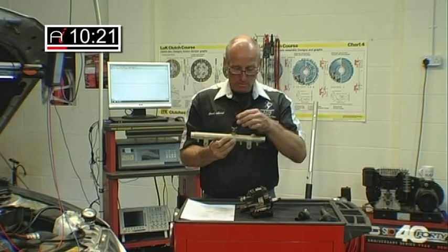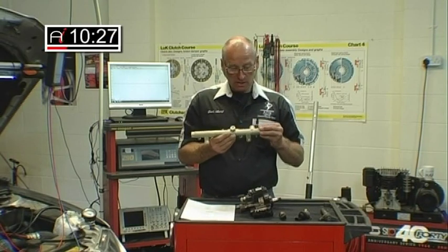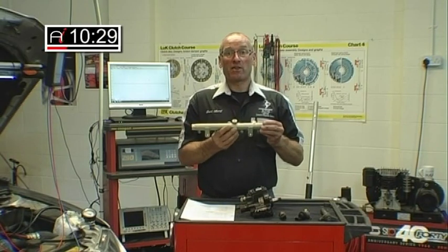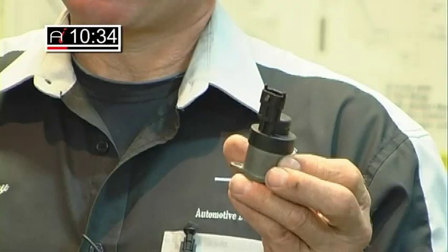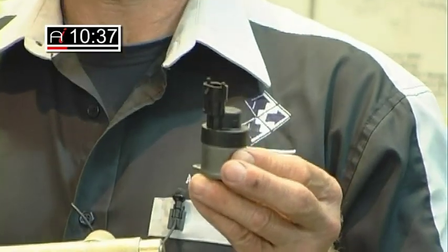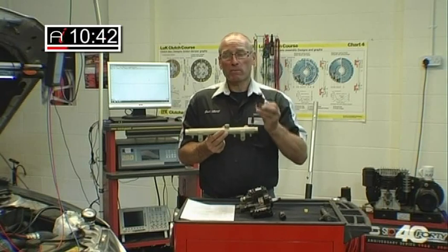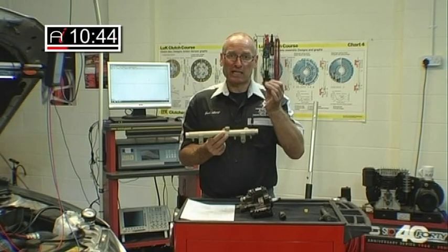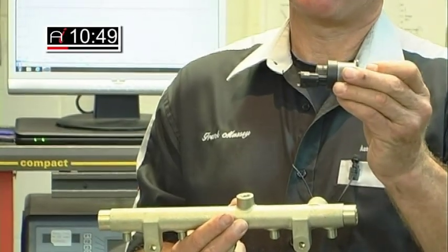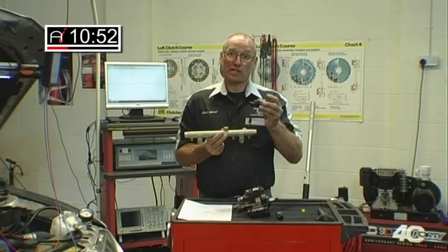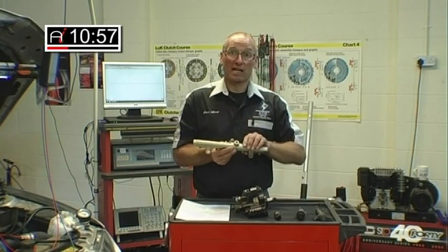Where that's important is that we can achieve the right voltage in the rail, therefore the right hydraulic pressure, at the expense of the incorrect duty. In other words, the pump may have to work harder than it should to create the pressure, potentially a leak or poor priming, or it could be the pressure's too high. The valve is mechanically sticking, or perhaps the escape route in some way is blocked, preventing escape of the diesel fuel, in which case the duty will be reduced. And that is not acceptable, so we need to monitor those two functions.